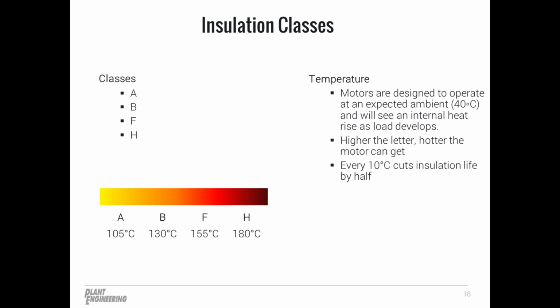But the bearings and other components would also be rated at temperatures above that insulation class rating. Looking at the NEMA rating specifically, since most of us here are in America, the higher the letter, the hotter the motor can get. In other words, a Class H insulation is rated to run at a higher temperature than a Class F insulation. So always pay attention to the motor's rated ambient temperature.